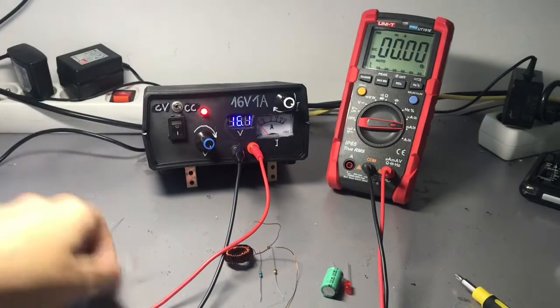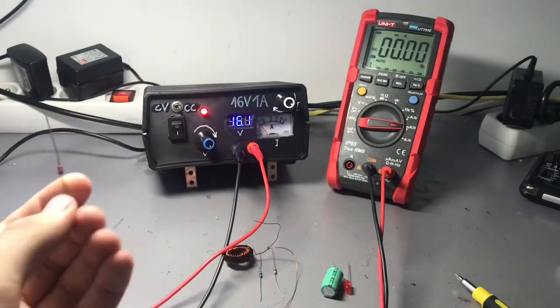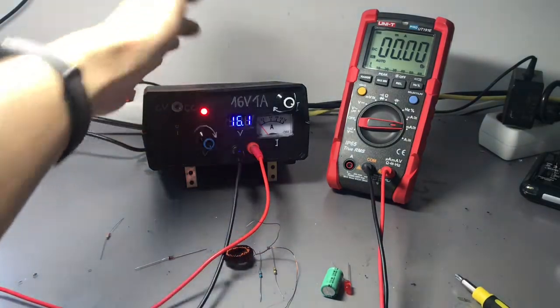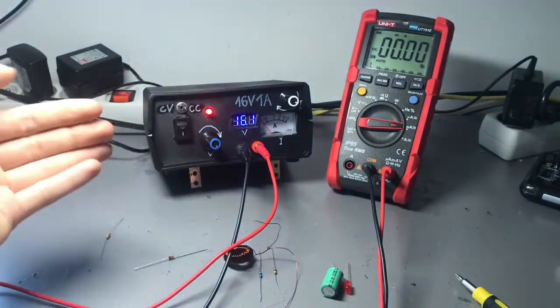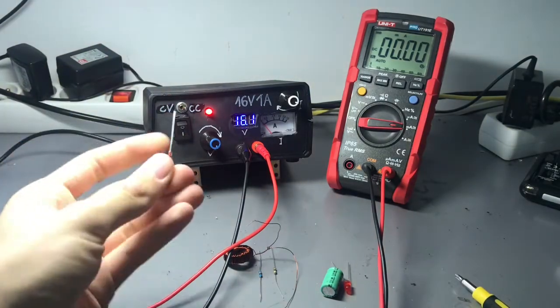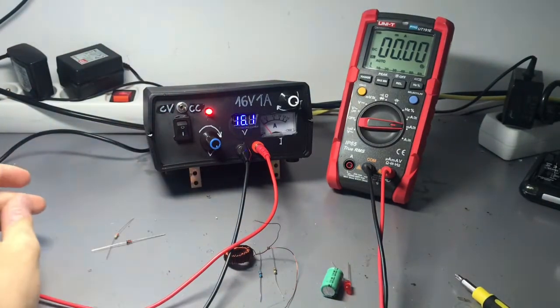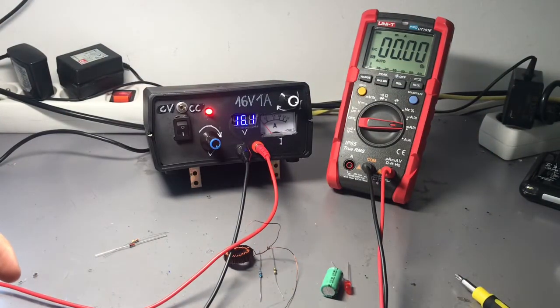But with a Zener, because of the current limit here, it stops increasing the voltage at 12 volts because of the losses on the transistor and stuff like that. So this is how we can test a Zener and the threshold voltage of the Zener when it starts to conduct the reverse bias voltage. So that's the DC side that we'll do.